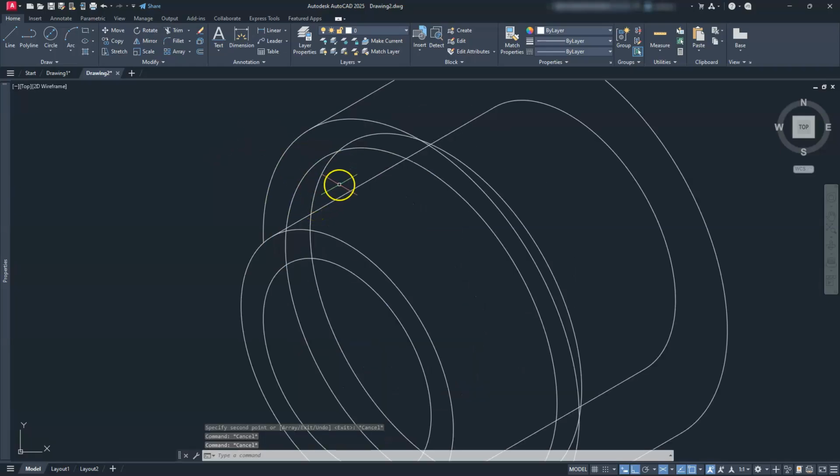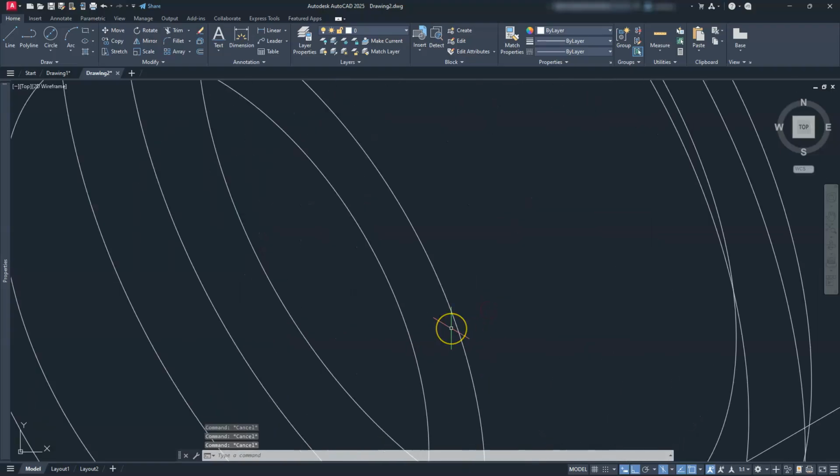And then I also have another ring on the inside of this, which is at 43, right? So I need to find the center of here, and then go ahead and put that ring here. Switch back to the ISO left, EL, enter, I, enter. Go and find the center of this one. So make sure you're seeing where that center is, which is located here. And then this one is our 43, right? So D, enter, 43. Okay. So now I have a lot of stuff kind of happening here.